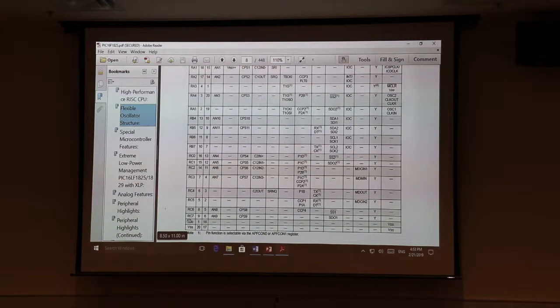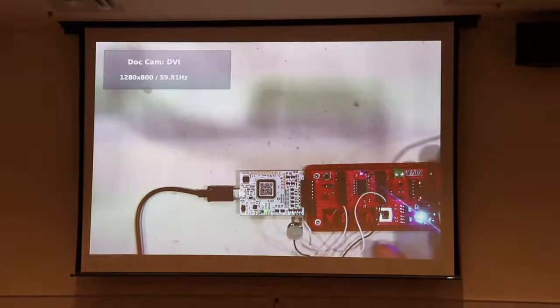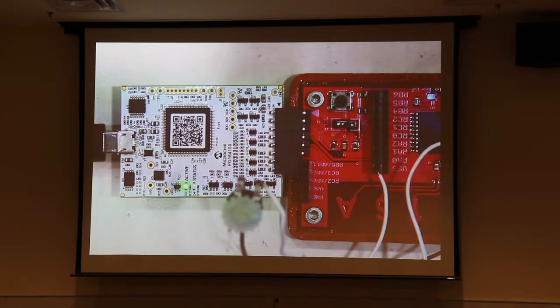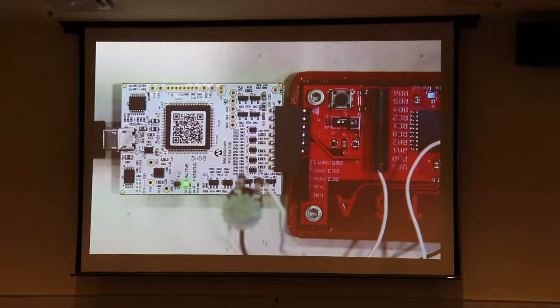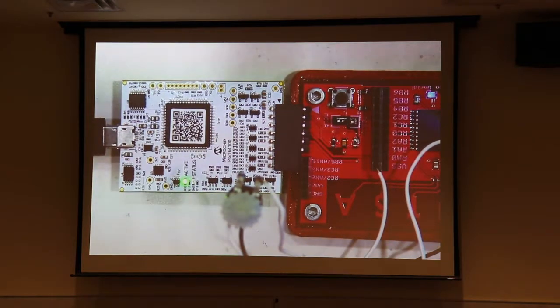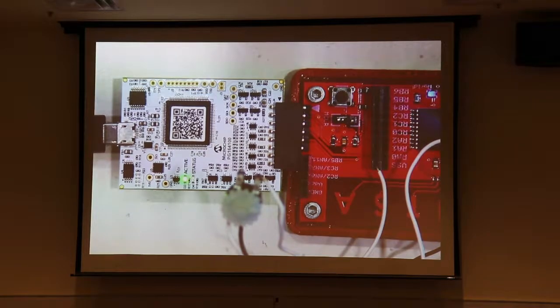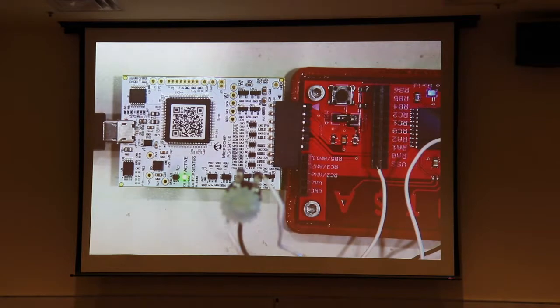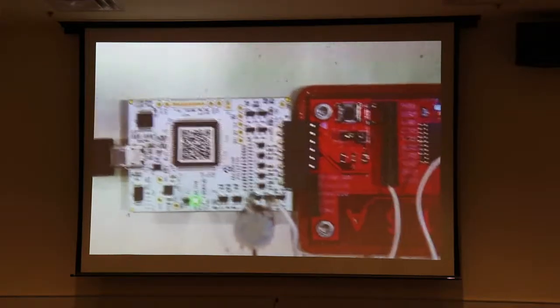Now if you look on the little board, we put both the AN number and the RC number on the little silk screen on your board. It's hard to read on mine because that red kind of screws it up, but you can see it's there. Can you see the letters there? So ground, power, and then RC2, AN6, RC3, AN7, and RB5, AN11. So it's AN6, 7, and 11 that are on your analog header.